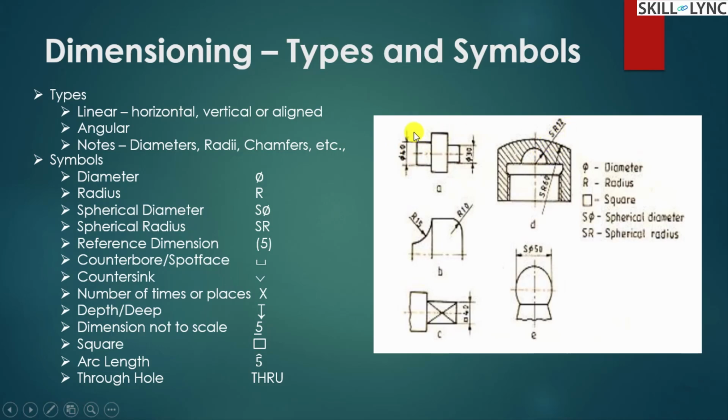And next, this object is a roller. The external, the bigger one, is shown as 40 diameter, whereas here it is shown as 30 diameter. And here we have different arcs. Here the arc radius is 15 for this feature and it is 10 for this fillet. So this is how you define your diameter and radius for an arcual element or a spherical element.